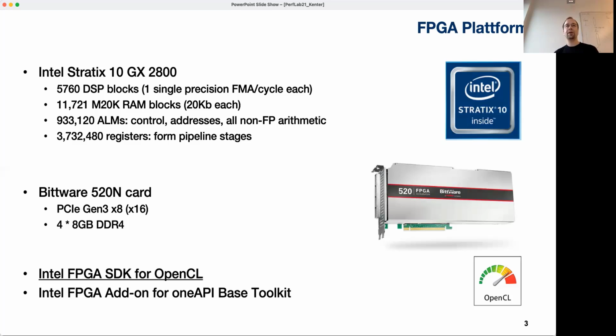In addition to these coarse-grained resources, the classical ingredient of FPGAs is logic, which are on the one hand lookup tables, which can perform any form of logic operation in a configurable way, and in between them many registers that allow to pipeline designs and hold intermediate values in state machines or in data flow approaches.